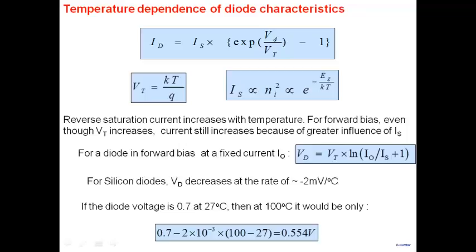So although I'm saying the ambient temperature is 50, inside your device the junction temperature may be 100 degrees. Okay, so don't think that this is an unnatural number here. In fact, the numbers can be much higher also, 125, 150, it could reach, depending on how the diode has been constructed, how efficiently it can release heat to the ambient here. All right, so that's something to keep in mind.